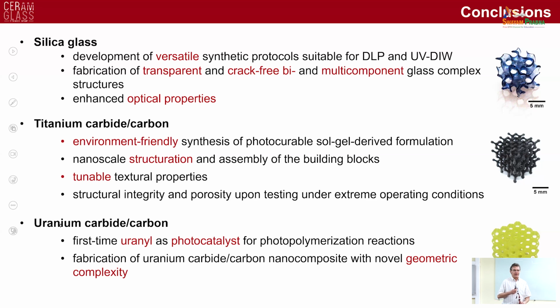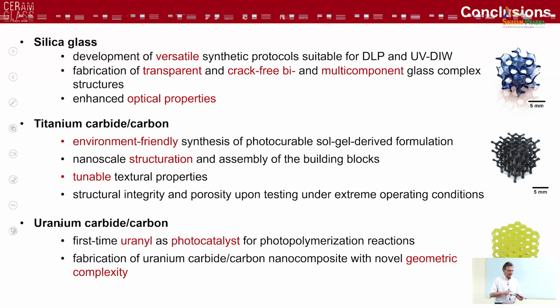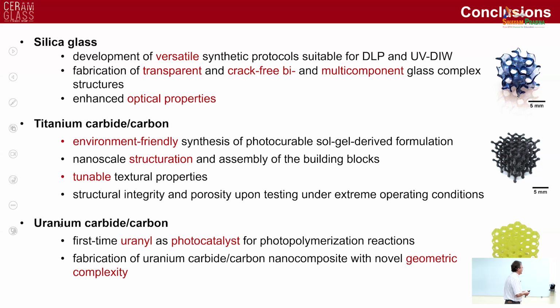But if you use colloidal silica, then you will not be able to dope that with an alkoxide to increase the refractive index, because you will obtain a crystalline material which is non-transparent. If you process in an atmosphere with a carbon source, then you can make carbides.